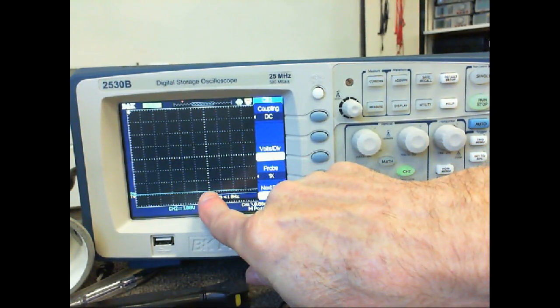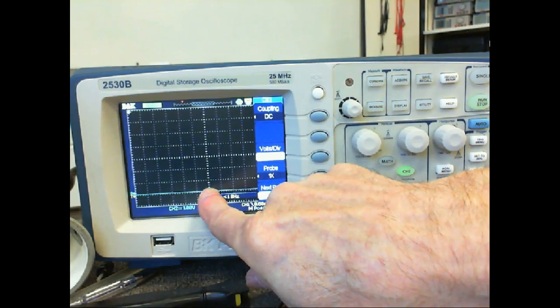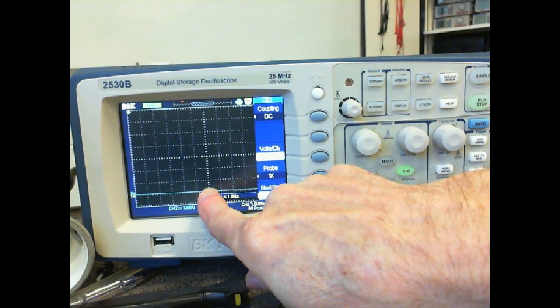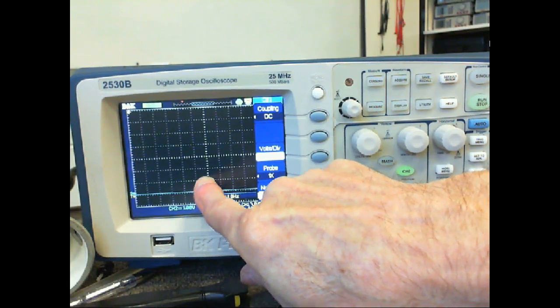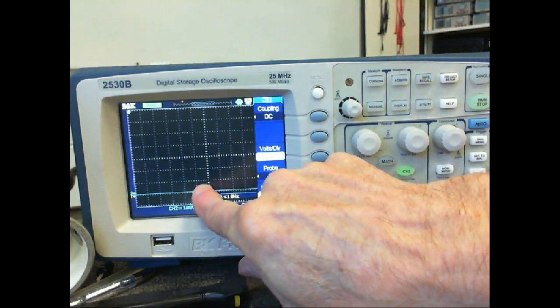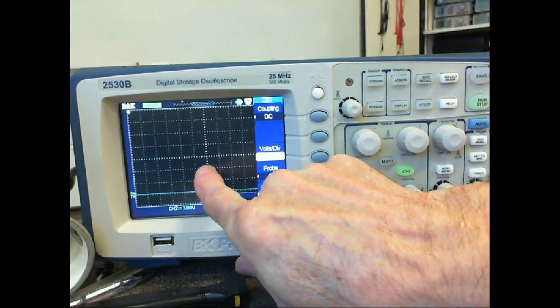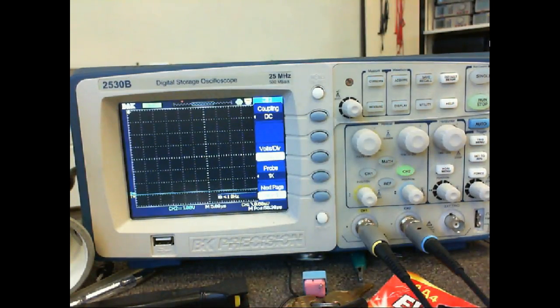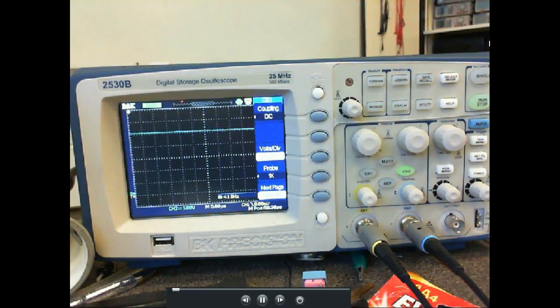Then basically that would be 1 volt. If this is 1 volt, and each one of these is 0.2, I know to get a legal 0, I'd have to be right there. And this right here would be 2 volts. In fact, we'll show you how to set it where you can see it real easy whether it's a legal high or legal low. Now what's nice about a scope